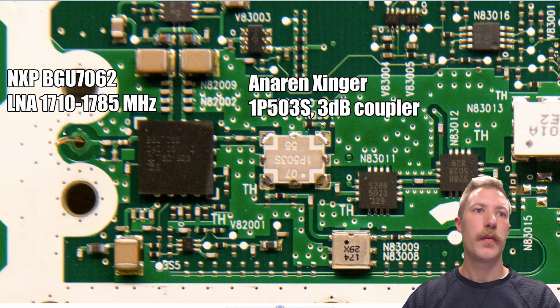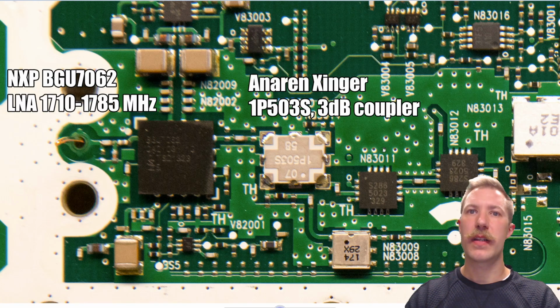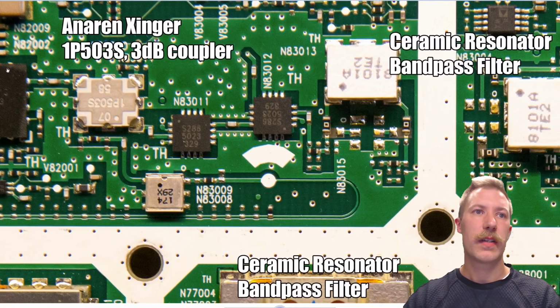Here we have the input from the duplexer, which goes directly into an NXP low noise amplifier, which has a very narrow working frequency bandwidth. From here we can see the big power supply rails sitting at top here. The signal exiting here goes through an Anaren Xinger 1P503S, which is a 3 dB hybrid coupler. Here we can see the phase change through the coupler.